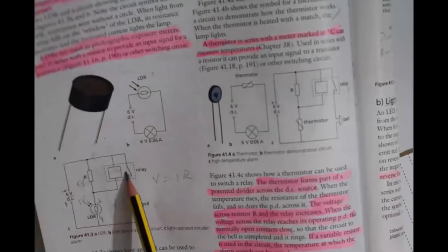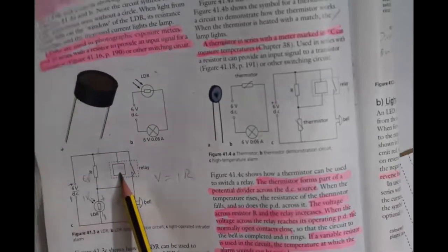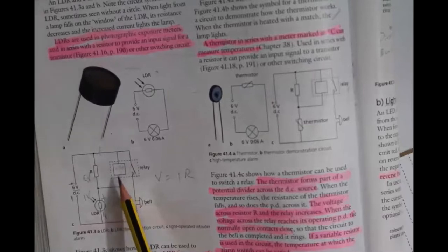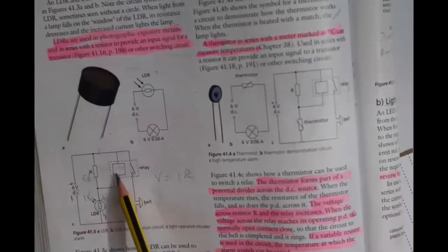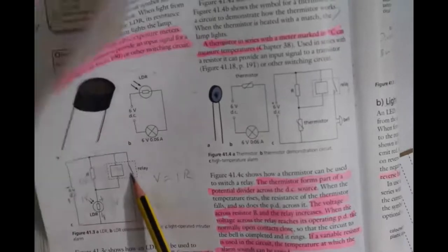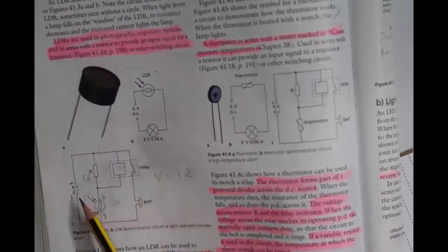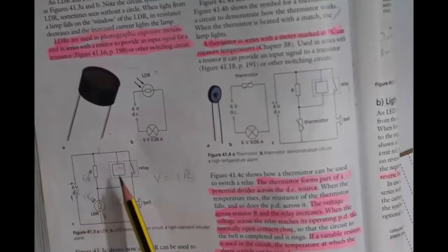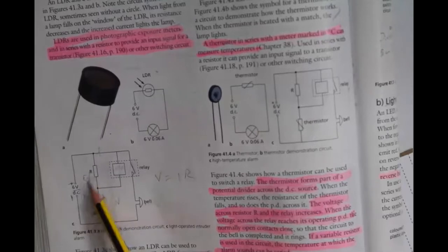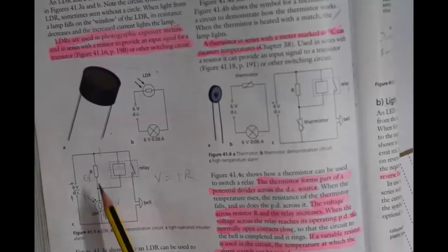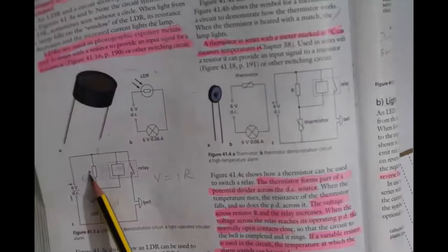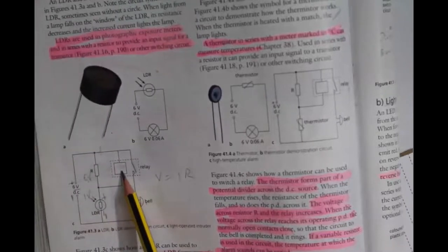And if this electromagnet reaches the potential difference at which it works, the potential difference that activates it and makes it magnetized, it's going to pull this piece of metal. So let's say that the potential difference at which it gets magnetized is 5 volts. Now that the circuit has reached 5 volts, that means the resistance of the LDR has dropped to a level where this other resistor now has a potential difference of 5 volts. And so this gets magnetized.